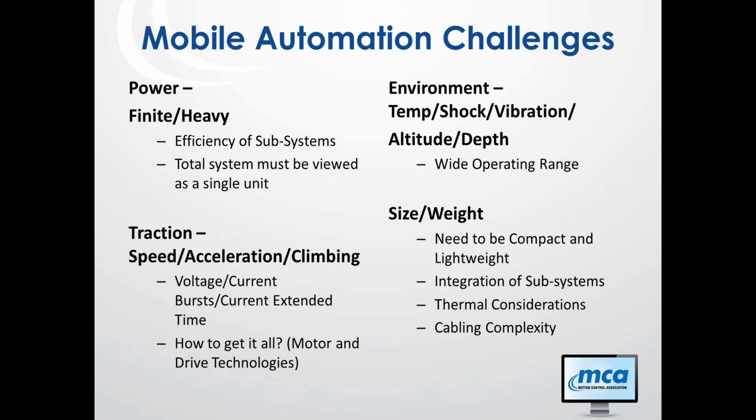I can give you speed and I can give you torque in a motor. I can't necessarily give you both. So how do you deal with that? You can do that with higher voltages in your battery supply, or we can do peak current, so it's got to be a finite time where we can climb the ramp or the stairs.